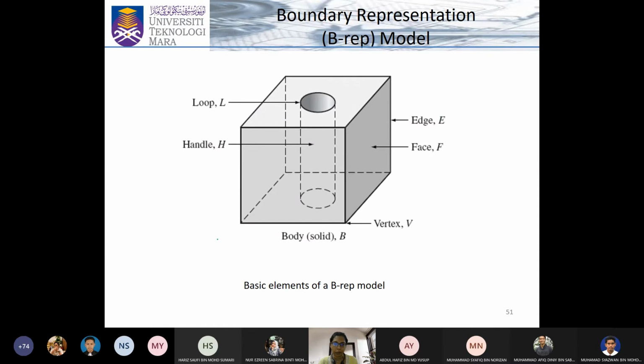Like this, you have your 4 corners. This is what you all will do in CATIA: you will draw a square, then take the square, exit, and give a vector, and it will extrude. Now it will finally form surfaces 1, 2, 3, 4, 5 top surface and 6 bottom surface. So this is the idea of a boundary representation model.